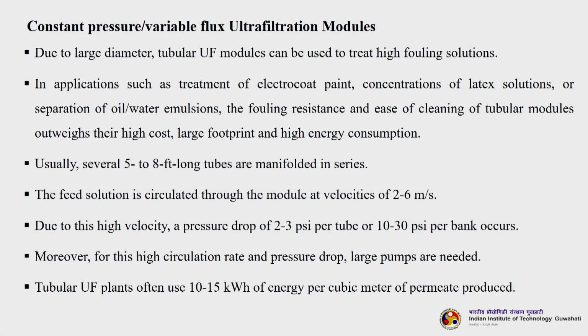Due to large diameter, tubular ultrafiltration modules can be used to treat high fouling solutions. In applications such as treatment of electrocoat paint, concentration of latex solutions or separation of oil water emulsions, the fouling resistance and ease of cleaning of tubular modules outweigh their cost, large footprint and high energy consumption. So, basically there will be a question coming to mind: what type of module and what type of membrane has to be used? As I told you many times, I am again repeating that the intended application will tell us what type of membrane as well as module we are going to use.